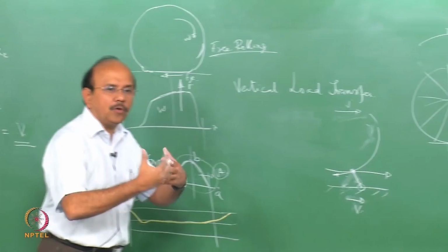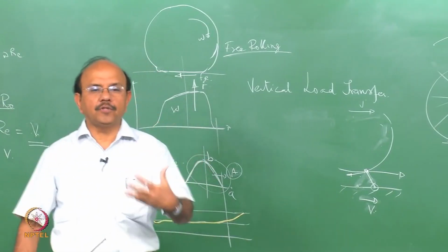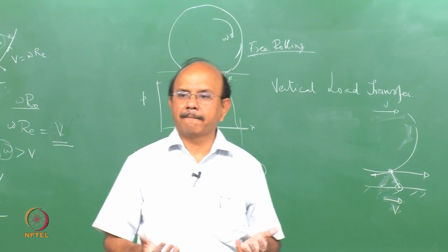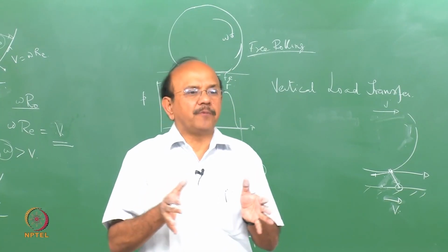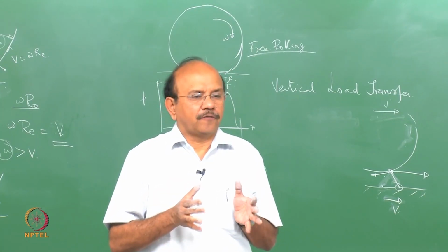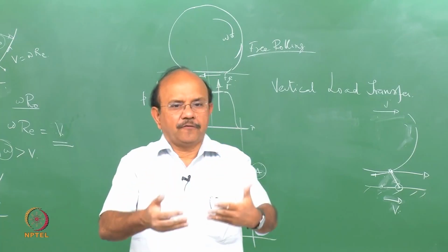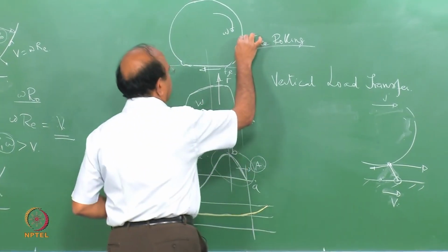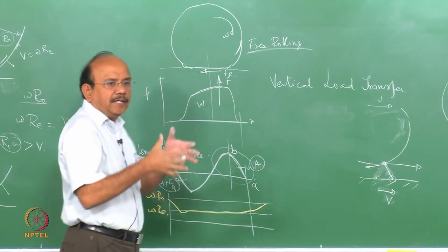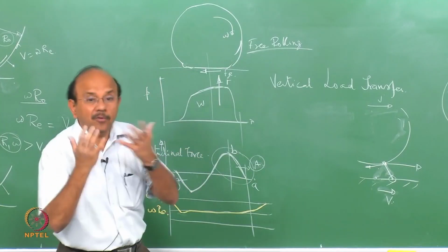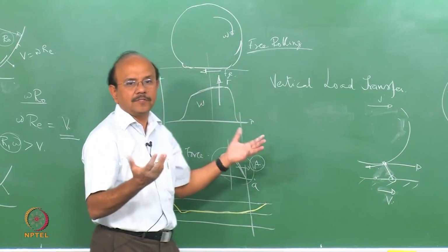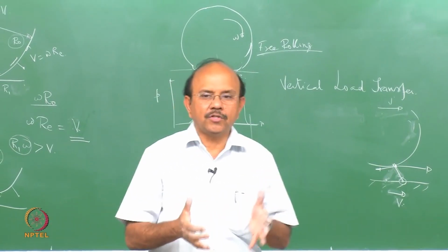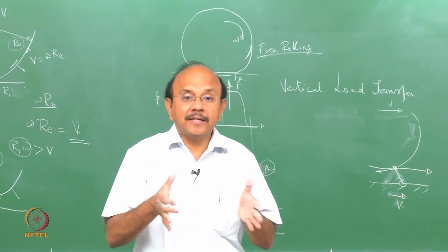So as I roll, and as I come to the contact patch, the radius is going to decrease and I'm going to get compressed, because after all, I am in a free, stress-free state. I'm just lying there. As I enter the contact patch, because I am a part of this circumference, obviously, my radius is going to change, so I will get compressed.